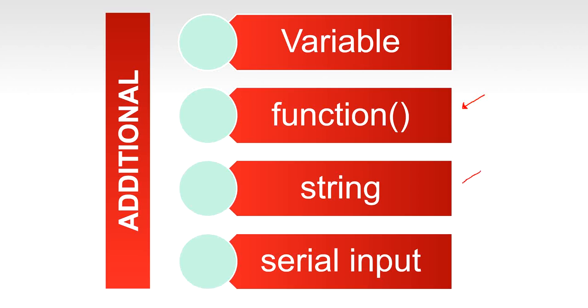The third part is the string. String manipulation will be quite important if we wish to develop an application that communicates via the serial communication protocol, in which when two microcontrollers or a PC and a microcontroller are connected, one of the media they can use to communicate is serial communication. The procedure will be that the PC sends a character to the Arduino, and then the Arduino needs to decode that character or string to determine which function can be executed based on the given command.